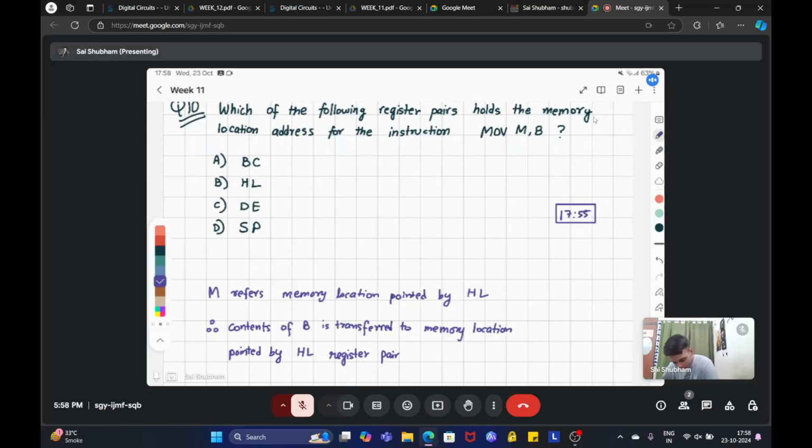Okay. So we have a couple of general purpose registers. One is the accumulator, another is register B and register C, which form a register pair. Then we have D and E also. Individually, they are 8 bits and can be operated independently, but we can also operate them together as a 16-bit register pair. Now we also have H and L, which are special because they act as a memory address. Fine. So these are our general purpose registers, including the accumulator.